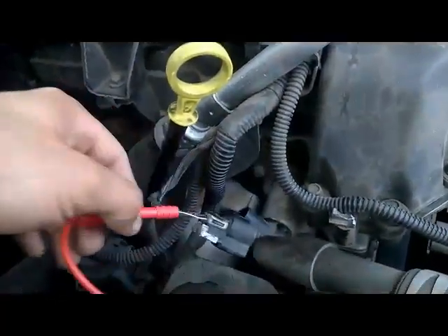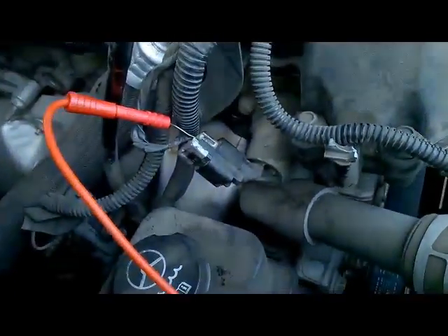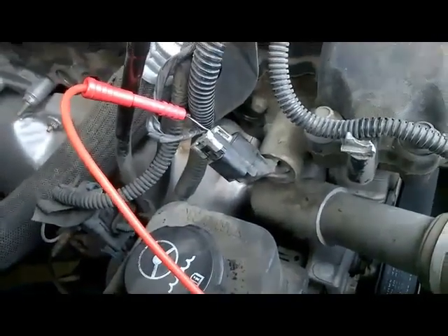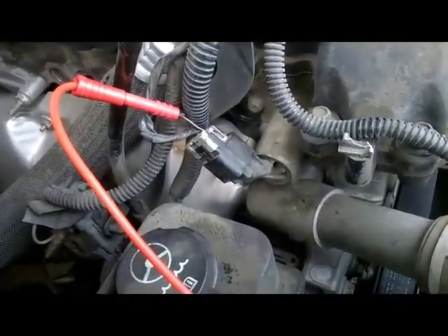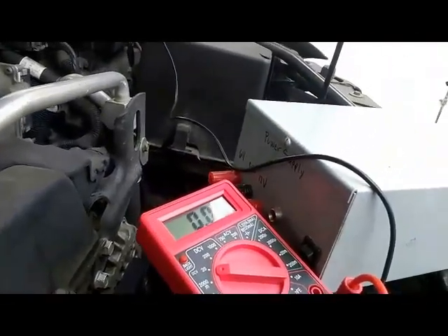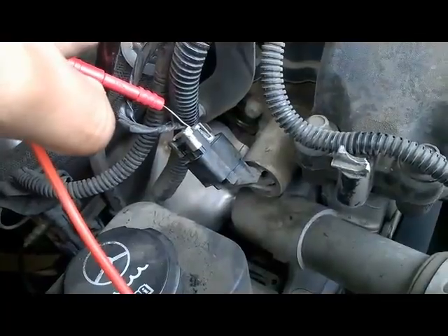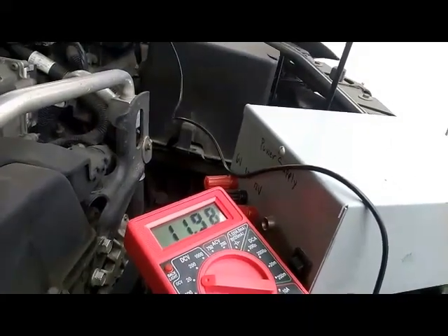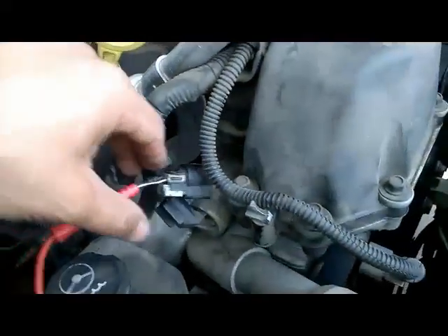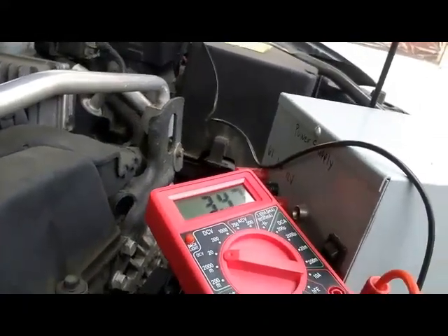Okay. So before I check the ground wire, since our connector came off, another way to check if our brown wire is our 12 volt source feed is to unplug it, and if our 0 volts jumps to approximately 12 volts, that's going to confirm that our brown wire is our 12 volt feed. So here we go. I'm going to unplug it. So as you see, our 0 volts jumped to approximately 12 volts. This is with the connector off. So I'm going to plug it back in, and it should go approximately back to 0 volts.